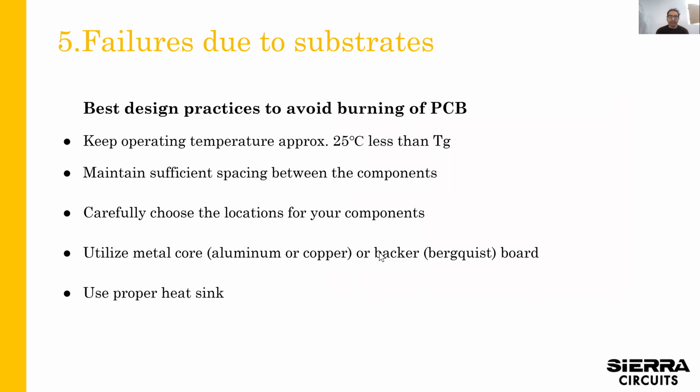And of course, best practices: place your components properly, making sure that you have enough space between the components. In this case, we're talking about heat, but you also need to space your components properly so you can test them okay, and get to your critical nets in order to probe and find out everything's okay. So component placement is always a key part of doing your design.